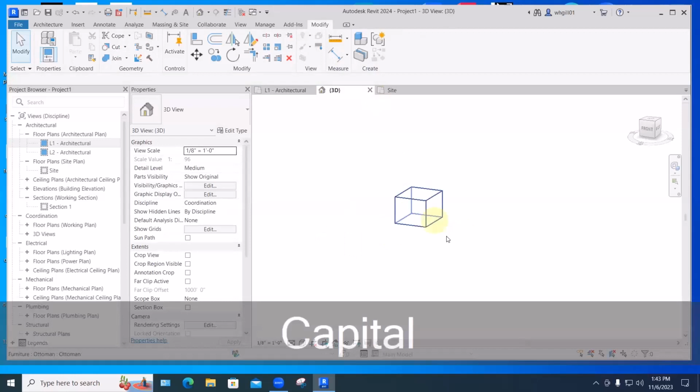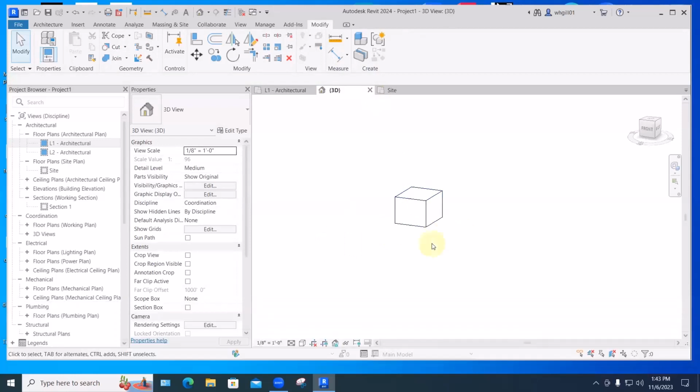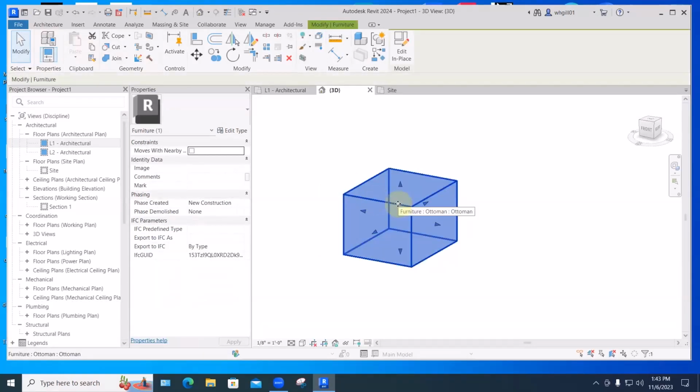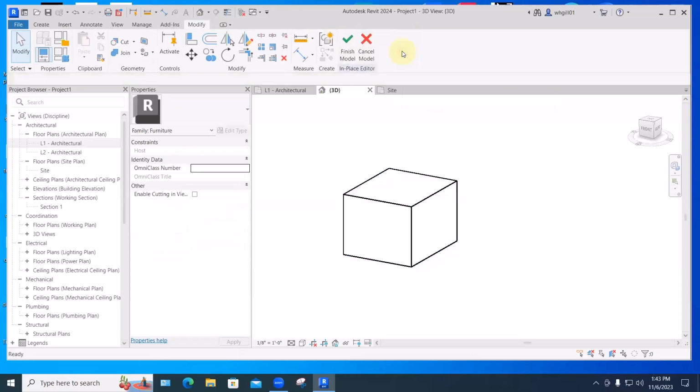And what I want to do with this is to round off the edges, the top edges, with, let's say, a 3-inch radius. So here I'm going to make a negative sweep around there. So pick this. Whenever you're modifying the geometry of something, you need to take it back to the environment where it was created. So if we did a model in place, then we need to edit in place. And so we've got that.